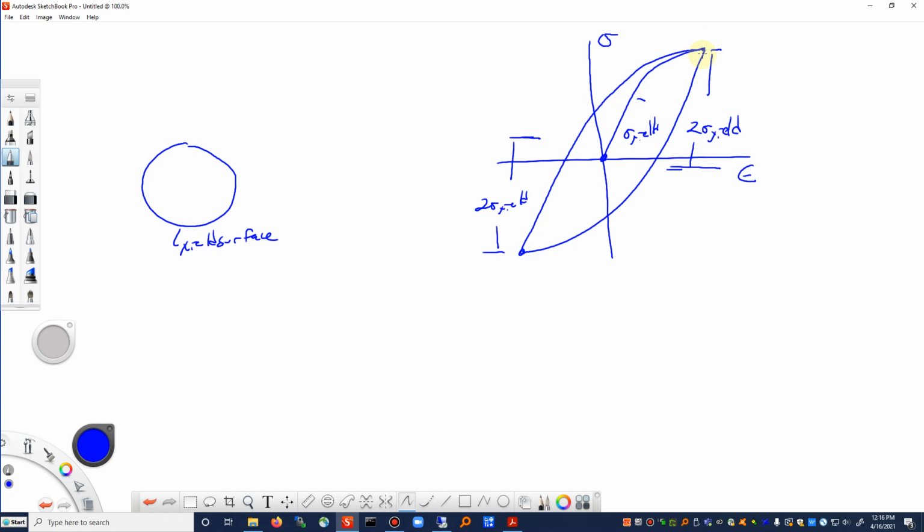When we talked about the Ramberg-Osgood equation, we have a continuous yield equation. This is a little different than what we have right now when we think about these yield surfaces. These yield surfaces, we have a well-defined elastic zone and a well-defined area where we have elastic and plastic behavior. Now we could think of this yield surface shrinking down to be tiny, tiny, tiny, and we would have a little bit of plastic strain everywhere. But from an implementation point of view, it's nice to have a finite yield zone, elastic zone size.